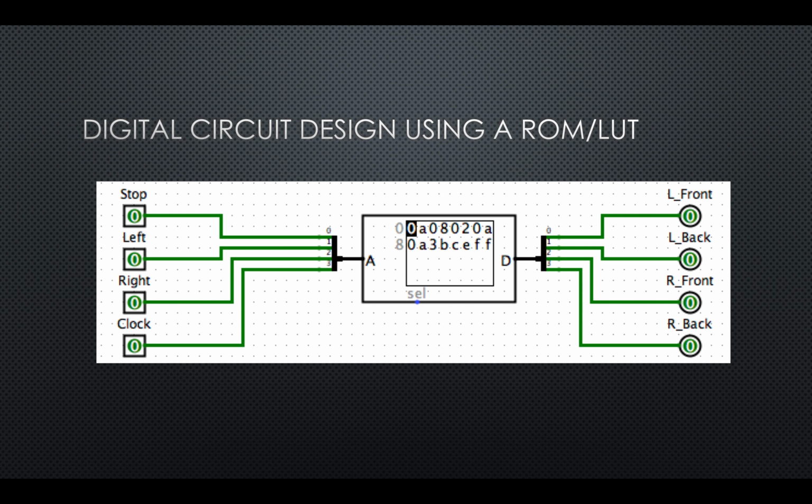Each of these cells is filled with a hexadecimal number, which corresponds to a number between 0 and 15. As the inputs change, the address changes, and the table looks at the cell that corresponds to that address. The value inside that cell is then converted back to a 4-bit binary number, which is our output with the most significant bit in the wire marked with number 3, so the 4th bit. We can see that while it is not applicable to every circuit, sometimes using a ROM can result in a cleaner circuit and simpler to read.